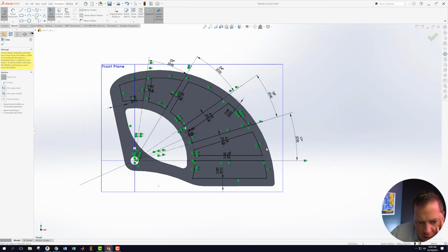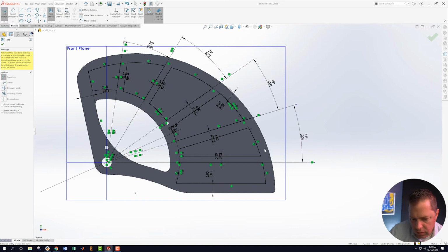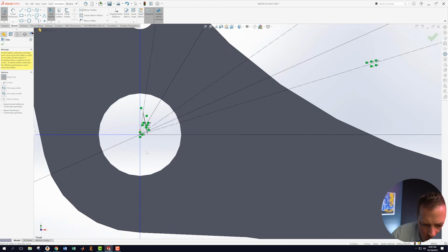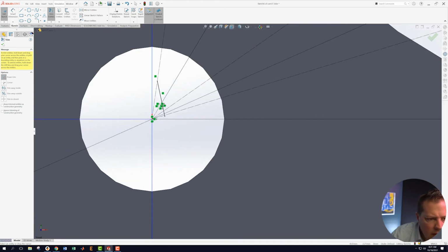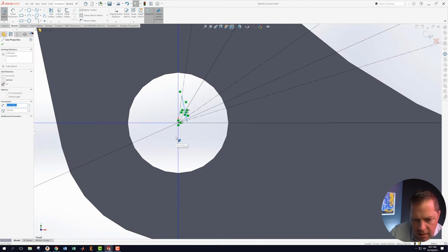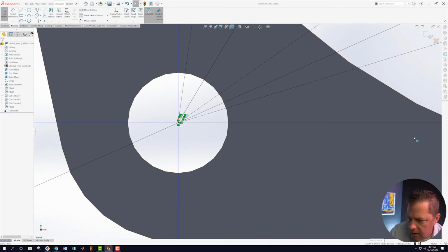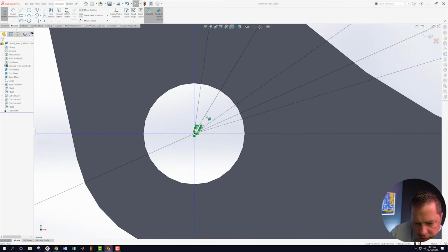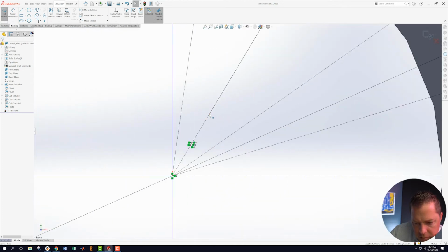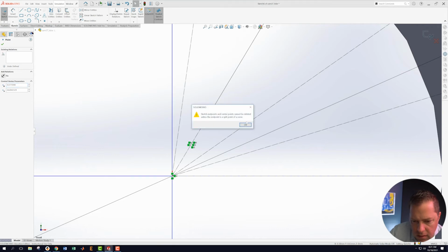Okay, first of all, everything's black. It's great, but it says underdefined. Why does it say underdefined? Okay, look, I've got this stupid thing hanging out right here. What is this? Delete that. Okay, I'm still showing as underdefined. Why? Because I've got a point right here. I don't know what that is. Just delete that thing. I don't want to delete that thing, apparently.